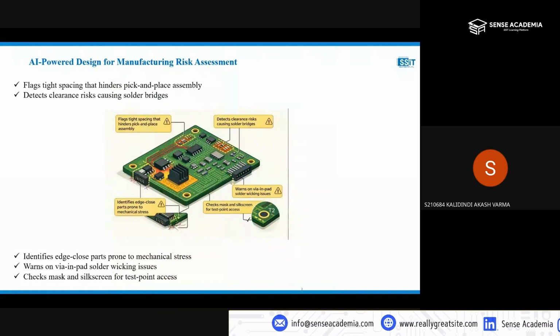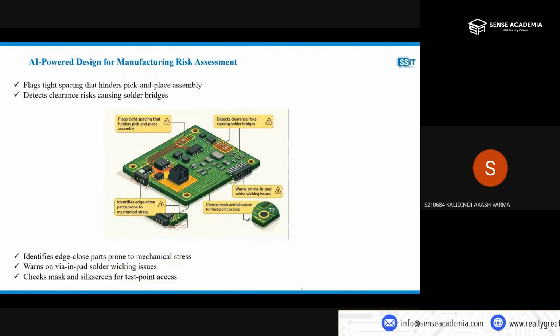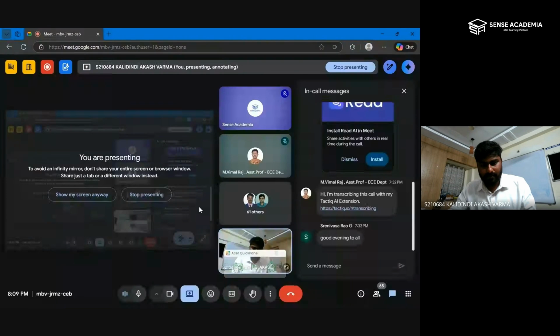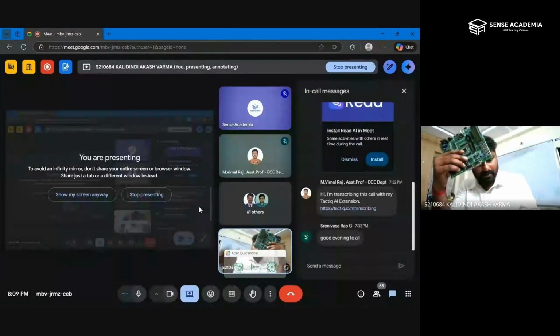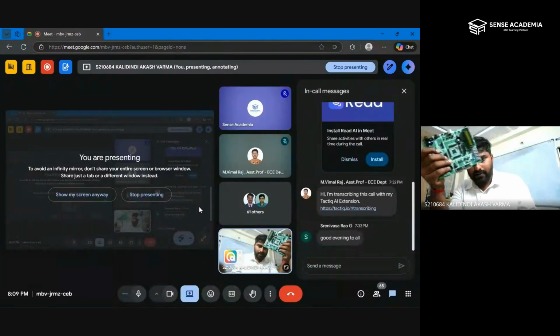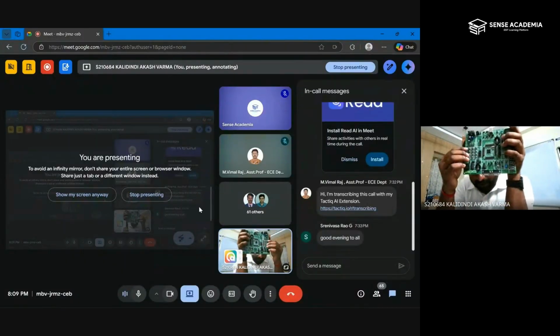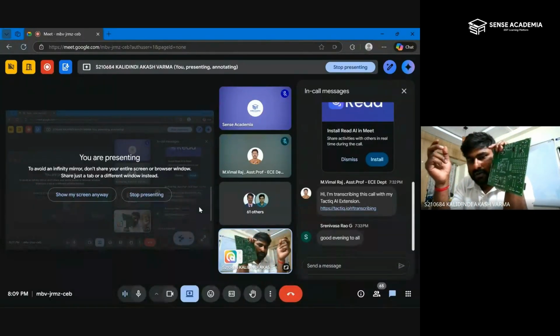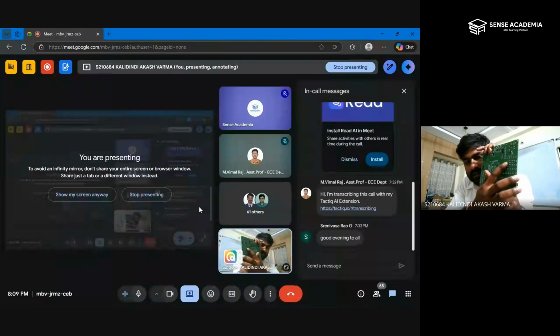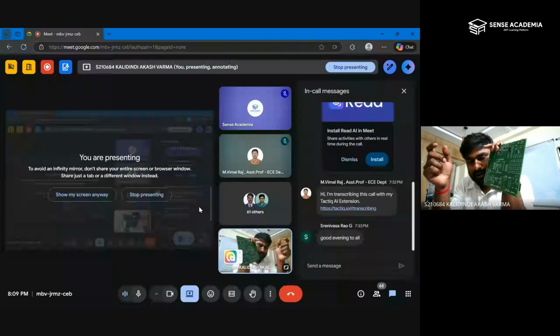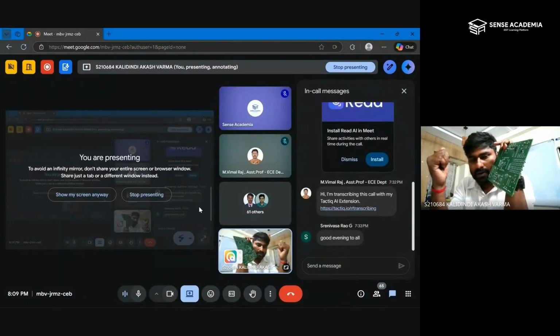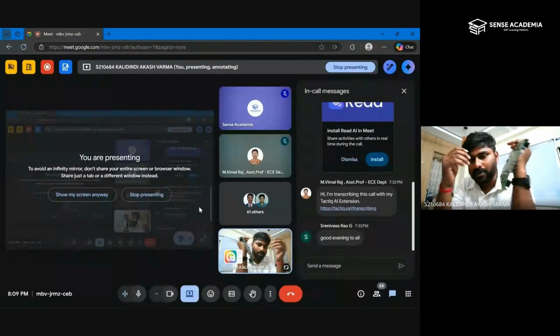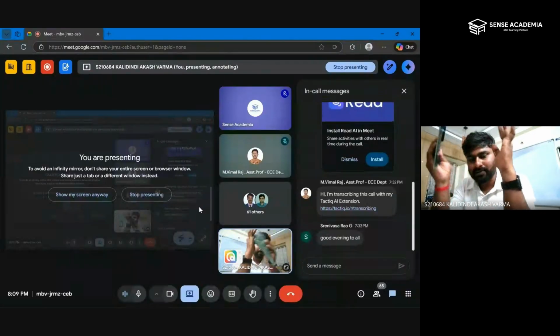The manufacturer sends the PCB. After sending this particular PCB, let me show our PCB again. So if we take this particular DIP component, some of the DIP components, if you are unable to follow the data sheet of the particular component, if you are unable to place proper spacing and proper footprint, then when we receive the component, the footprint is mismatched. The component is unable to fit in this particular PCB, so the entire PCB will be damaged.